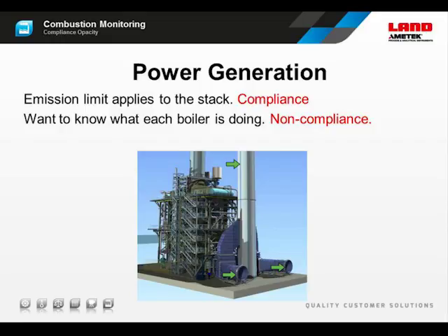So we would have a compliance opacity monitor, the 4500 Mark III, on the stack, and non-compliance monitors for process measurements on each of the flues. And the nice thing about the Land products is that the 4500 Mark III and the 4200 Plus share a lot of common components, so circuit boards, detectors, and power supplies can be interchanged between the 4200 Plus and the 4500 Mark III. So only one spares holding is needed, even if they've actually got the two different products.